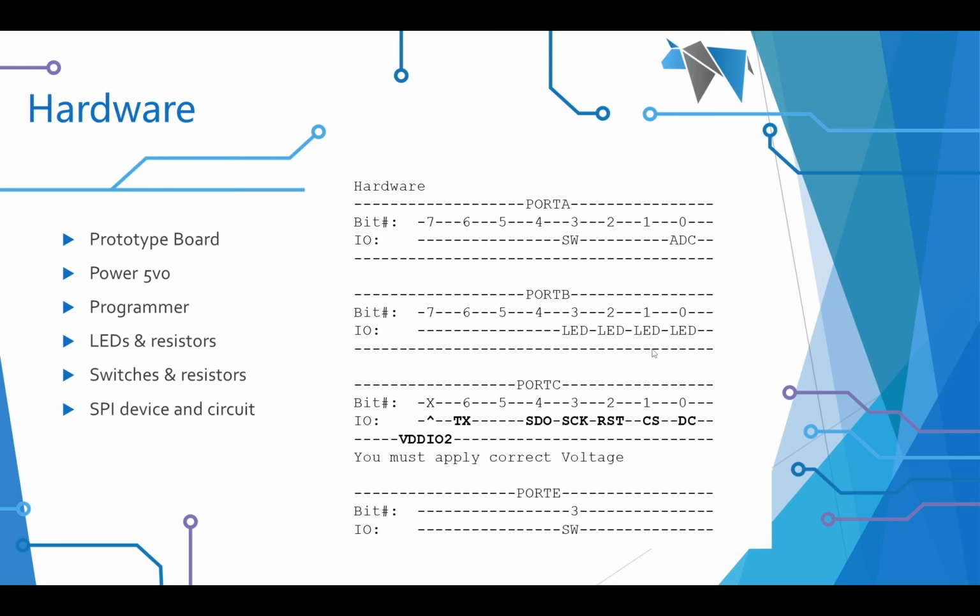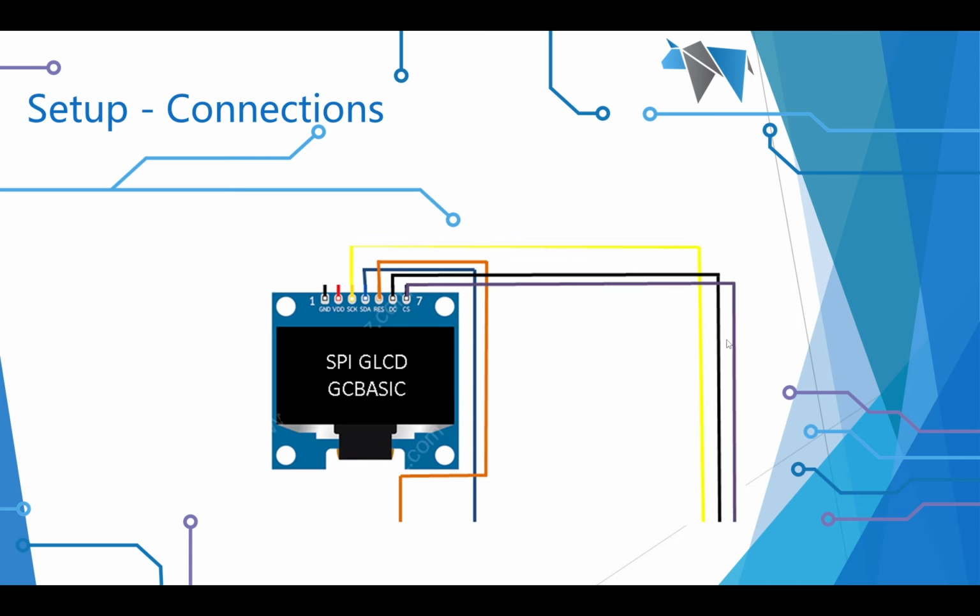Depending on what the protocol is doing, it's going to toggle that data and command line, and it will then inform the target device what to do. If I'm sending a command, you'd actually raise the signal, and for data, you lower the signal. And all that's part of the protocol that's supported within the SPI communications itself.